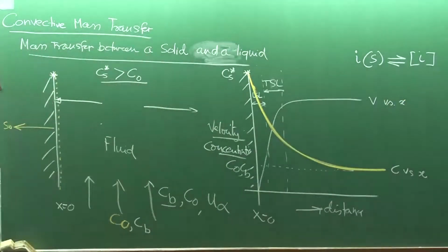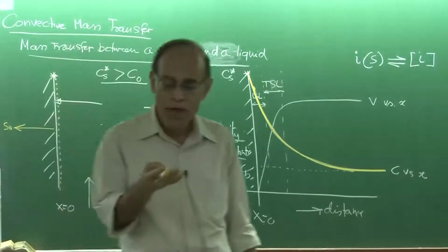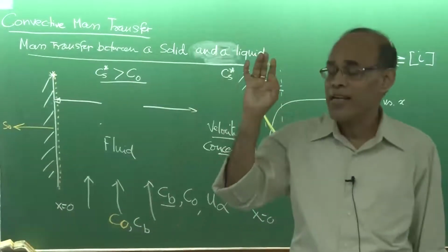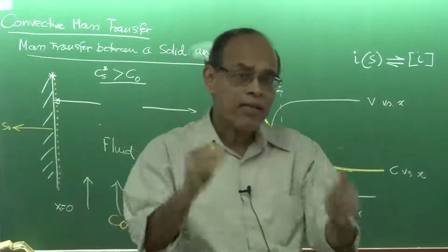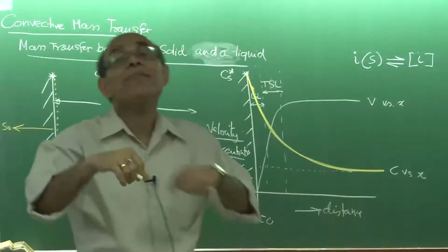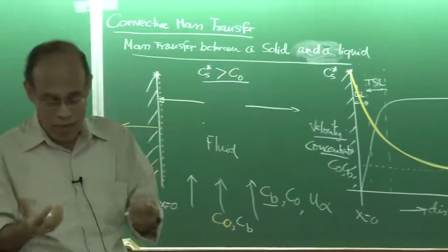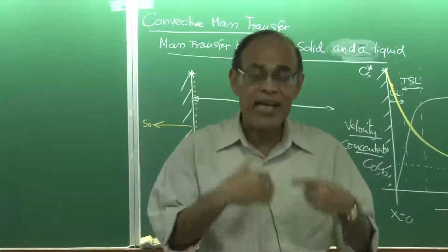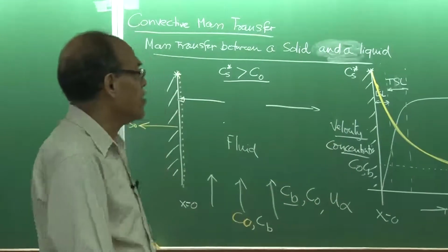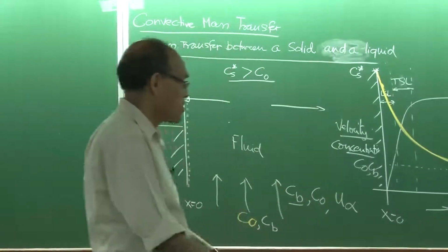Now, what are the mechanisms of mass transfer? The mass transfer mechanisms are diffusion and convection. These I have already stated categorically in my first lecture. But convection we can split into two parts: one is laminar convection, and the other is turbulent convection. I have also said, particularly in the context of heat transfer, that the rate of turbulent heat transfer is far greater than laminar heat transfer, because of the simple fact that superimposed on the mean motion there are eddying motions in the system.